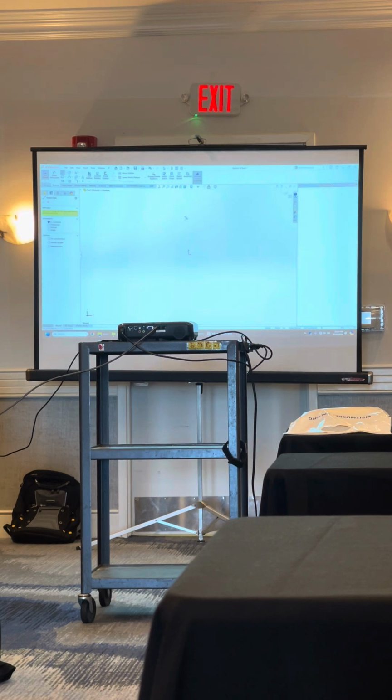If I were going to draw a slot without using the slot tool, I would start by drawing a line, right? Then when I have that other line here and I need to turn it into a tangent arc, not just an arc, it has to be tangent, I move my mouse pointer back to where the line started. I don't click a button, I don't push anything, but now when I sweep out, I have a tangent arc. So I can come around and quickly put that in, do the swing out, come around. Now, the problem you might run into is that you might swing it out the wrong way. No need to hit escape and redo it. You simply move your mouse back and pull it in the right direction just by resetting it. Again, no button clicks, nothing.